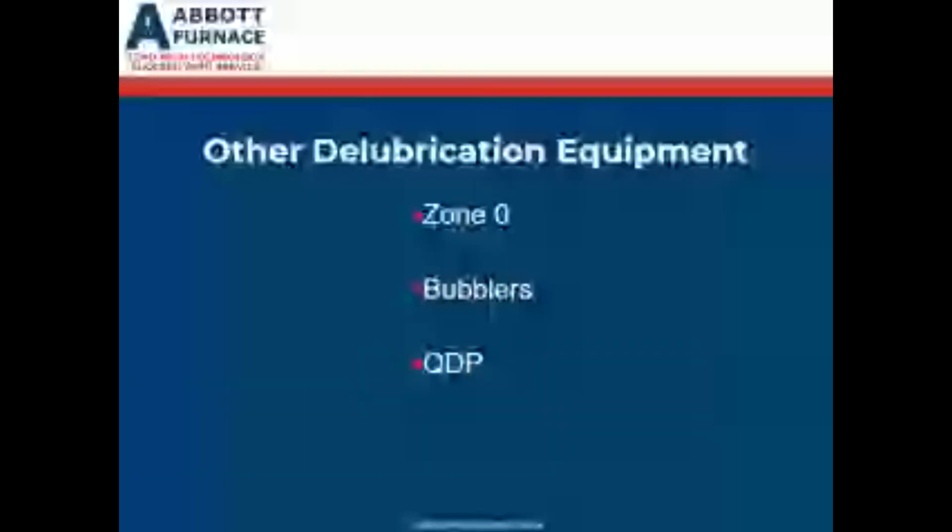Another assist you could use is from a bubbler or a fast unit, where we inject a little bit of water vapor or oxygen in the front there, and that oxygen reacts with the carbon vapors, it'll form CO2 and CO, and then that gas can be flushed through the hood and out the stack, as opposed to allowing the carbon to form a solid and having the buildup.